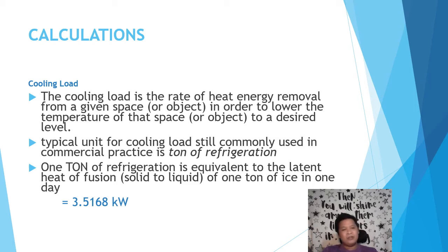So if you do the math for that based on the heat of fusion of ice for 1,000 kilos divided by the number of seconds in a day, you'd get a value of 3.5168 kilowatts or kilojoules per second.